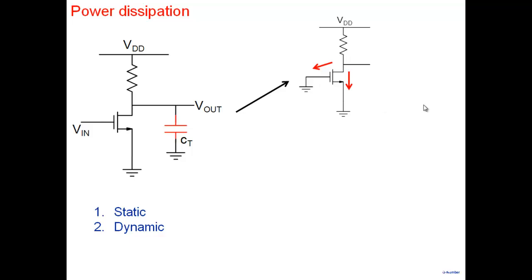The field across that oxide will become very high, will exceed the breakdown voltage of the oxide, and this would be leaking. So in fact, for these modern transistors, 3.3 is very high. You can't apply 3.3. They'll work with 1 volt. That's it. You can't go to 2 volt. 2 volt, if you put here, the gate oxide will break down.